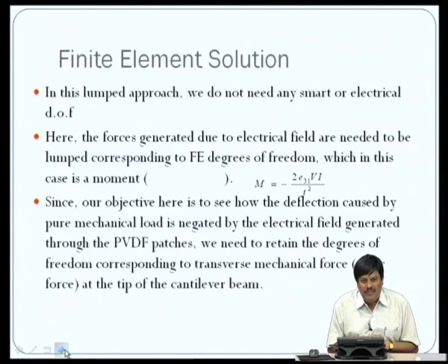Now let us do the finite element solution. As I said, in this lumped approach we need not use any smart or electrical degree of freedom. Here the forces generated due to the electrical field need to be lumped onto the corresponding finite element degrees of freedom, which in this case is the moment M, given by this expression.